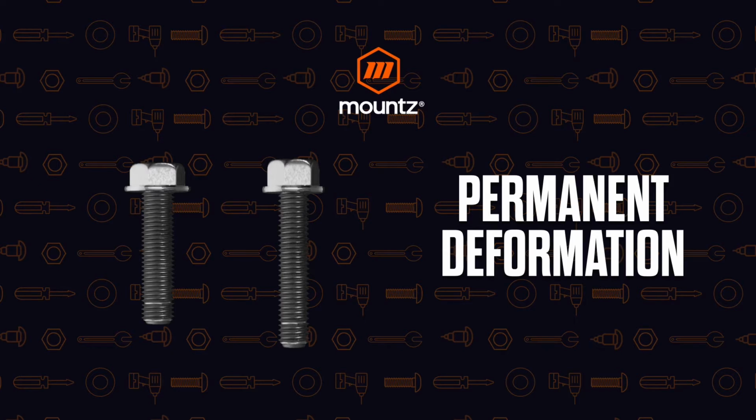And that's very important, because if your torque values are right around the yield point and you go over it, any type of shock or vibration to that fastener could cause that bolt to break, or the fastener to come out of its location, based on either the strength of the fastener itself or the strength of the material that it's in.